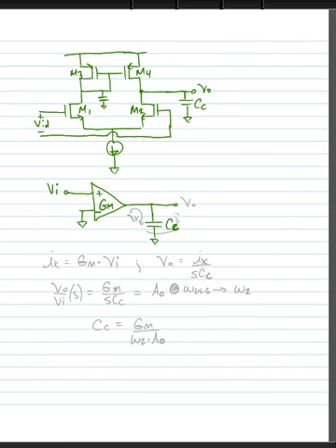So the goal here, first let's find what our voltage gain is. Our GM generator here is going to cause a current to flow, IX, into our capacitor, and it will create a voltage across the capacitor, which will be our output voltage. So we know that IX is simply equal to the GM times the input voltage. And we know that the output voltage, Vout, is equal to Ix divided by SCC, which is the same as saying Ix times the impedance of the capacitance.